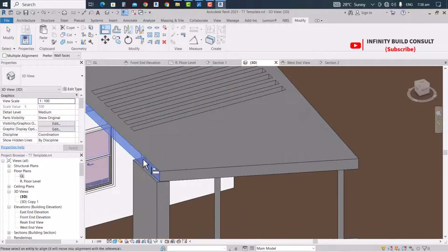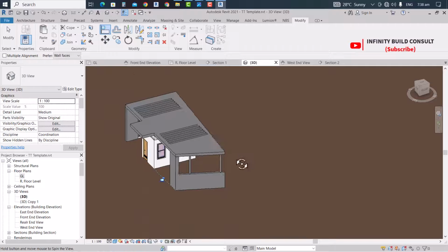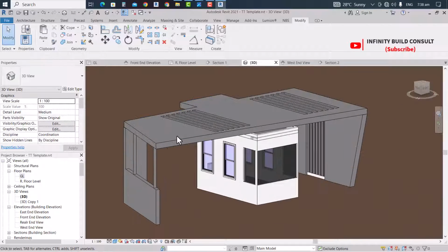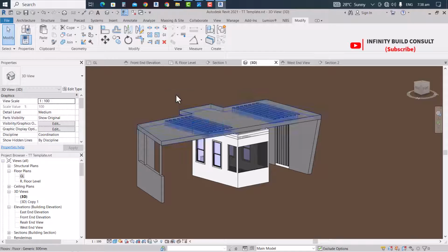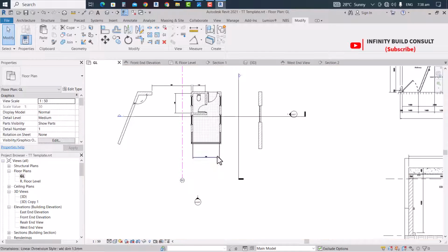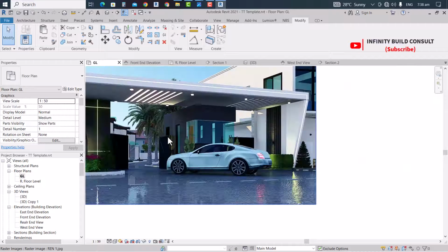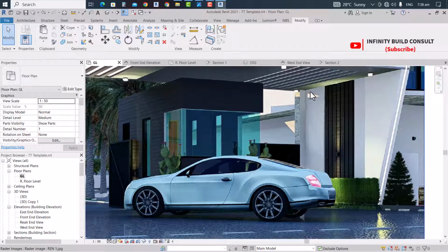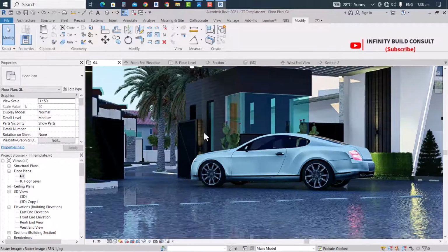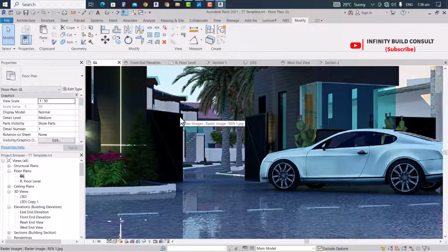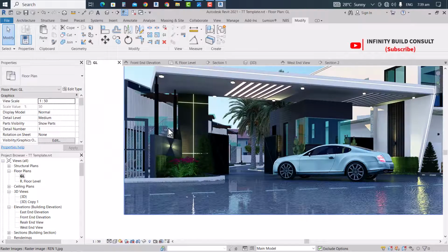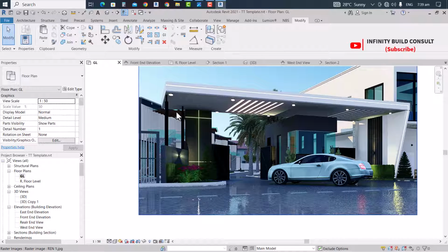Do AL to align this wall. So now we can compare this one and see if you are creating the right thing. So it seems we have a wall here which we have not created, and we also have some small walls holding the gate. So I'm going to create those walls here for us.